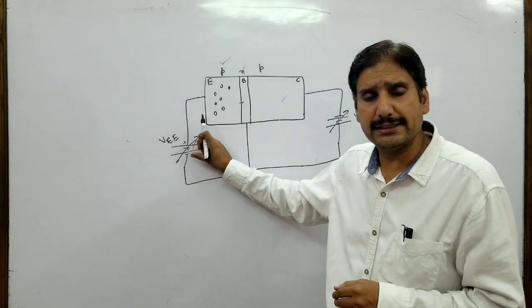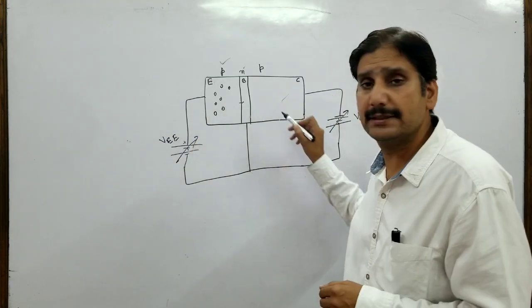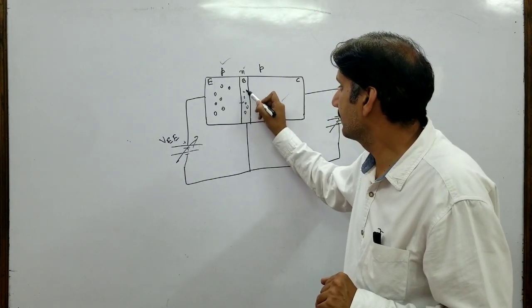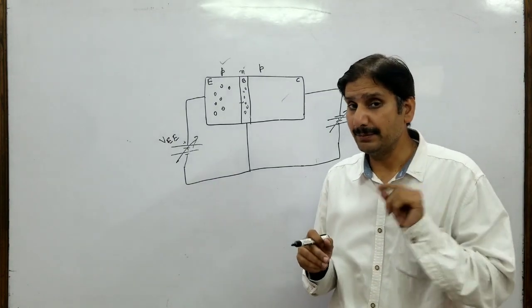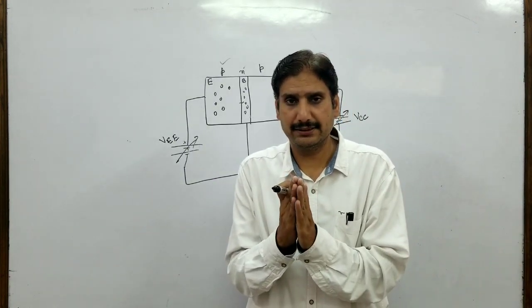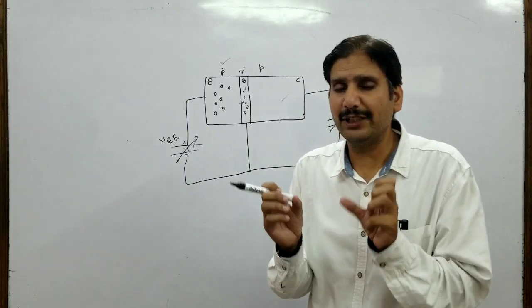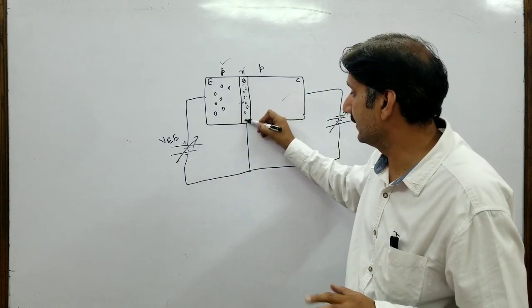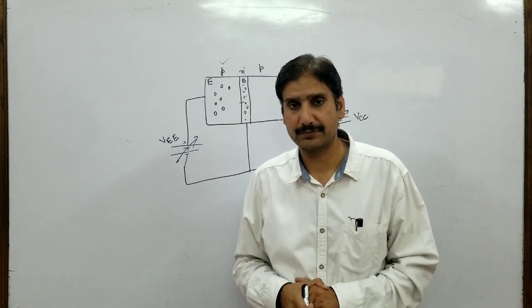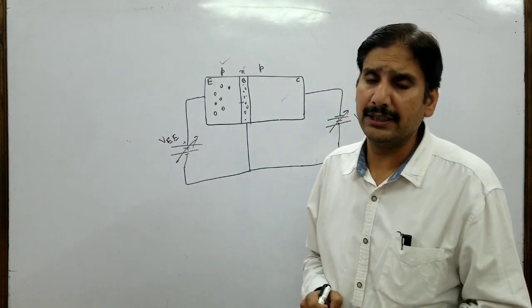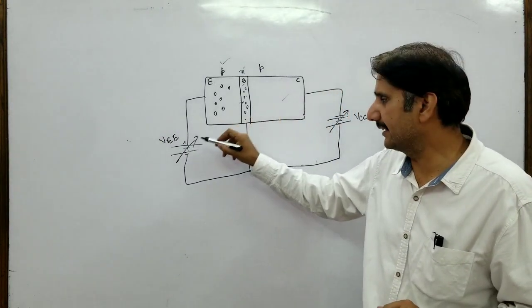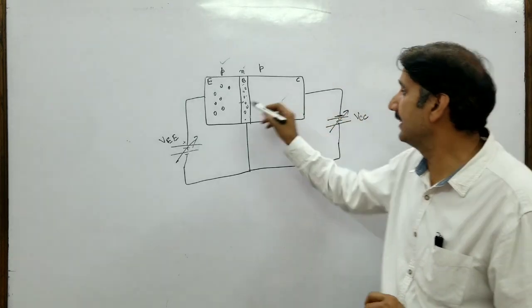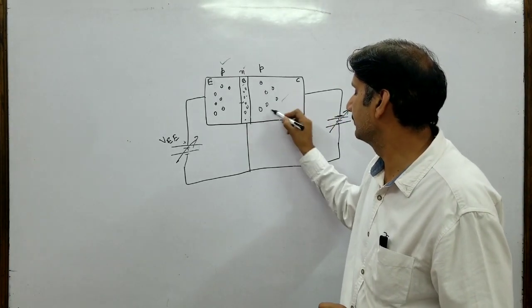So when this voltage is sufficient to push these holes across this junction to cross over that barrier, these holes reach the base region. But remember, the base region is physically very, very thin, and further it is very lightly doped. So there are not enough electrons in the base region to neutralize these 100 holes. Only 2 to 5% of them get neutralized, and the remaining, under the repulsion of this force and under the attraction of the negative terminal of the VCC battery, reach the collector region.